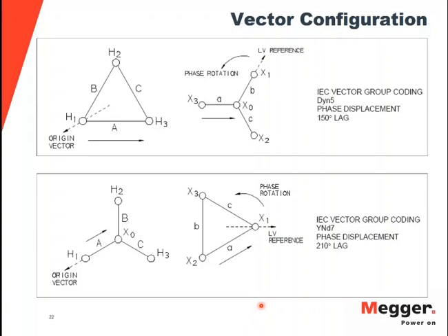Okay, thank you, Diego. Next question is for Dinesh. Recently, we were doing factory testing for a transformer with a tertiary winding rated for 35% of nameplate kVA. We observed similar voltage dependence as described here. Is this sort of voltage dependence expected for all transformers with a tertiary winding, or only those with tertiary ratings less than 20%?